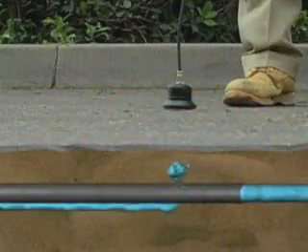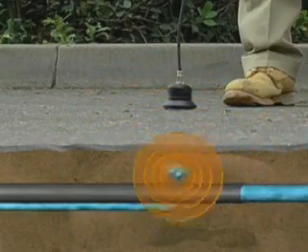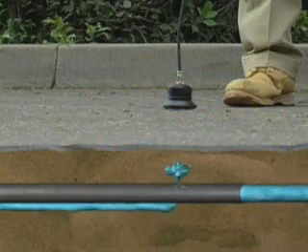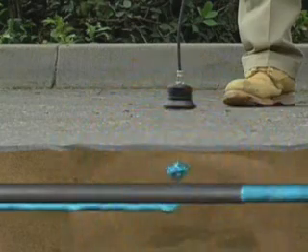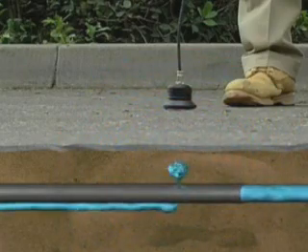First, let's start with the inside line on leaks. Leak sounds are created by three different situations. The vibration of the pipe caused by water forced through a crack in the pipe. This is the loudest and easiest leak to detect because it sounds like a whoosh or a hiss.